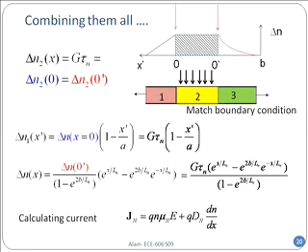In most cases, what is going to happen is the reverse is going to happen. Let's say you have a little detector you have just built, and the Kobe satellite or some satellite is going out in outer space. You have designed your little semiconductor detector. You put it in the spacecraft, it goes out, and then there's these cosmic showers coming down, right? And on the outside of the device, you have a little ammeter. The ammeter is telling you how much current is flowing. From that, you back calculate what cosmic ray radiation is coming through.